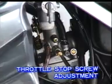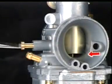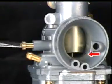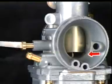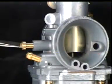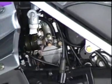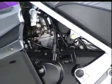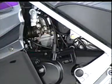Turning the throttle stop screw, on the other hand, causes the throttle valve to move up and down, and this changes the amount of fuel-air mixture sent to the engine, thus changing the engine speed. Therefore, both of these screws are turned to adjust the idling speed so that the right mixture of air and fuel can be obtained.